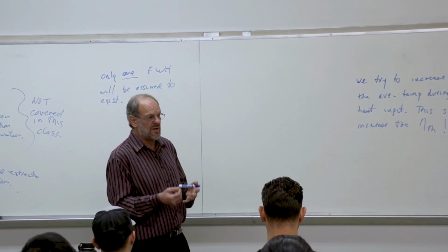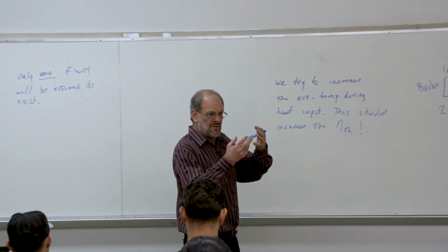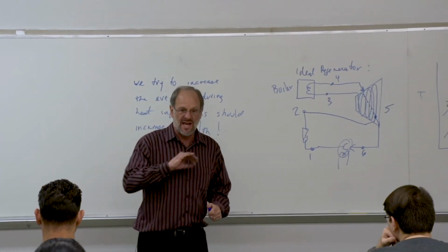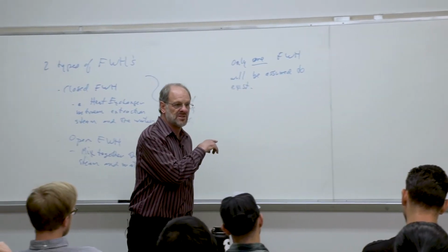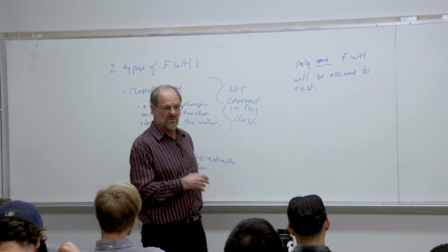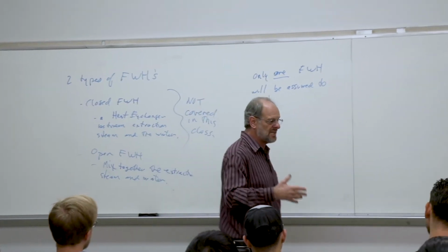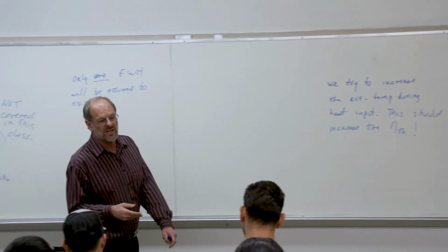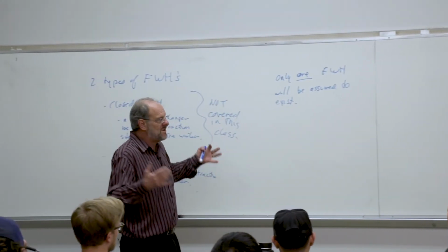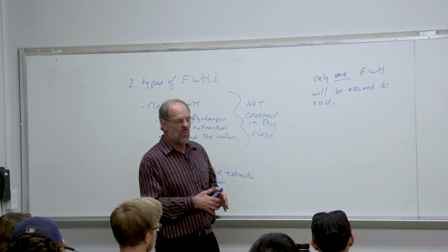Lower pressure water can't hold as much gas, so the gas comes out of solution. So it's air that becomes a problem. Any air that exists within our water streams will cause at least the potential for corrosion issues, right? Air will oxidize metals. So you have corrosion issues, you have the potential for explosive mixtures. You don't want any air dissolved into that water.